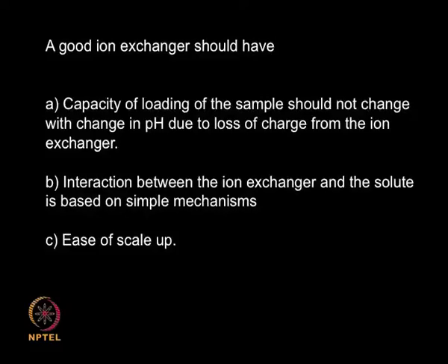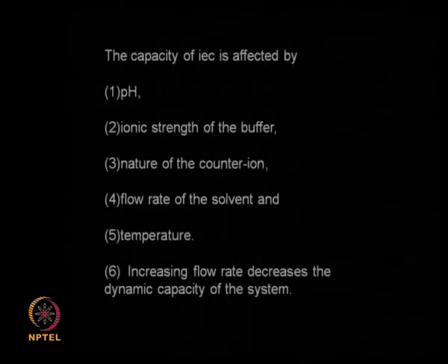A good ion exchanger should have a loading capacity of the sample that should not change with the change in pH. So change in pH should not affect the capacity of the loading, or cause loss of charge from the ion exchanger. Interaction between ion exchanger and the solute should be based on a simple mechanism. It should be easy to scale up, because I may want to do an exchange in a very small lab scale setup, then scale it up to a very large manufacturing setup. So it should be easy to scale up.